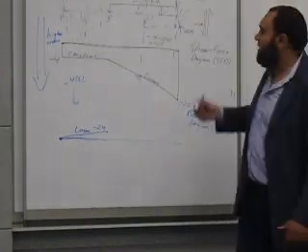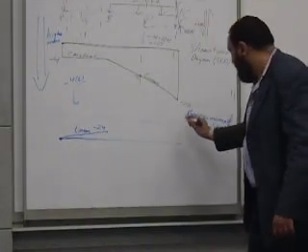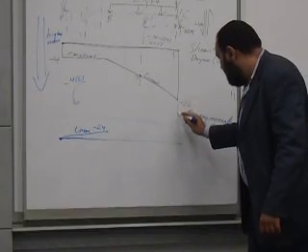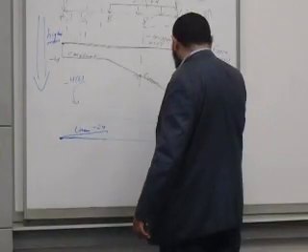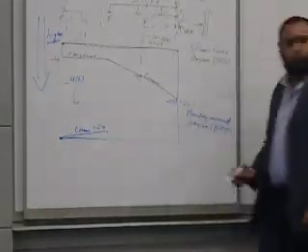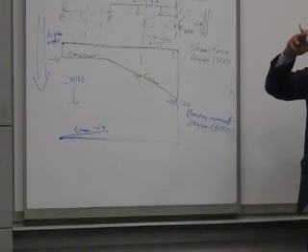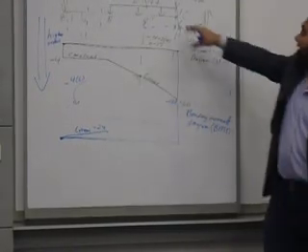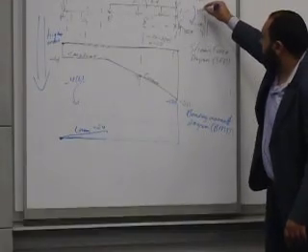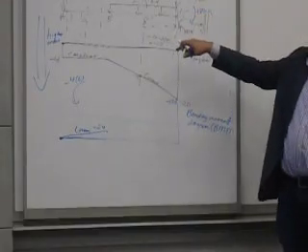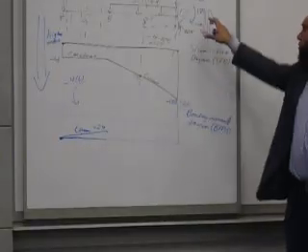Okay? The units here are kip-feet. Look now, ladies. I have here this negative 120. And because this is a fixation, be careful: if you go and actually calculate the moment reaction here, you will find it at 120. The moment reaction at C, at the fixation, you will find it to be 120. So this must be equal to the moment reaction.